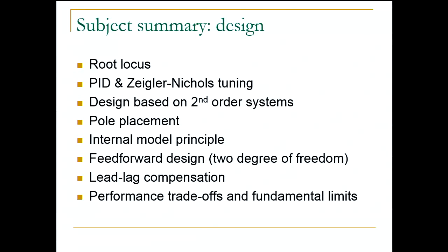And after that, we concentrated on controller design for second-order systems. So we related poles of a second-order system to overshoot, rise time, and settling time, right? So locations of poles were related to these features of the step response.